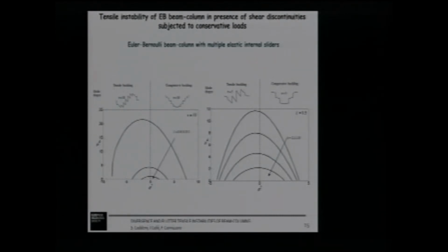For example, in this case, we have the eigenfrequency curves for 10 equally spaced elastic sliders for different values of the compliance. And on the right, we have, for a given value of the compliance, the eigenfrequency curves for an increasing number of equally spaced sliders.